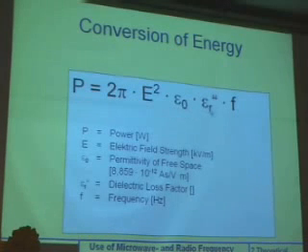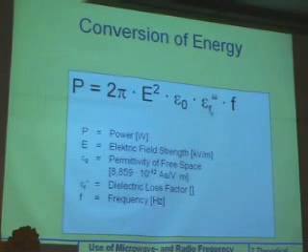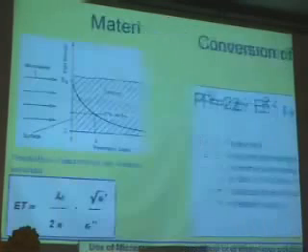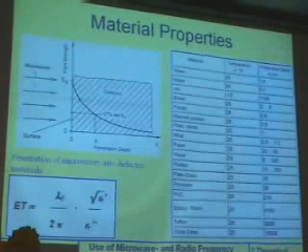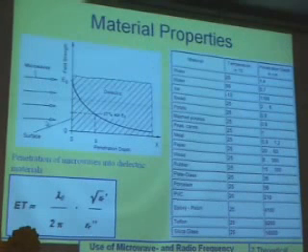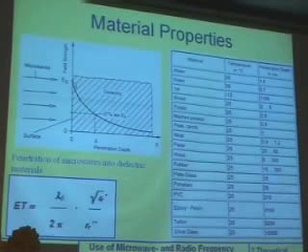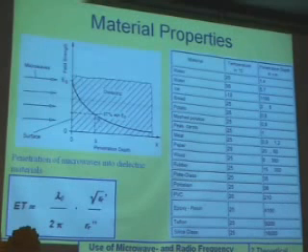The higher the loss factor, the more energy is attenuated in the product, and so we try to get energy in the product. But this has consequences, and I will show these consequences immediately. If you look in the way how microwaves and also radio frequency waves enter dielectric materials, like an agricultural product, can be a fruit, can be wheat or something like this, a potato. We will have a clear look on potatoes later. You will see that the way how the microwave energy penetrates the product is following the slope of a 1 through E function, of an exponential function.